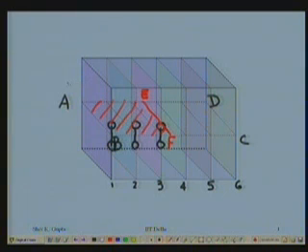After I have done this, all the bonds are cut. Top part of the crystal I push with reference to the bottom part of the crystal with a force, so that this first plane is shifted on this place by one interplanar spacing, by that much distance. I pushed it hard. After I have done pushing, just introduce some glue in this region and allow the bonds to form again, and see what happens when I do that.